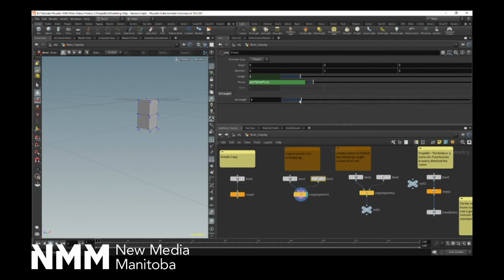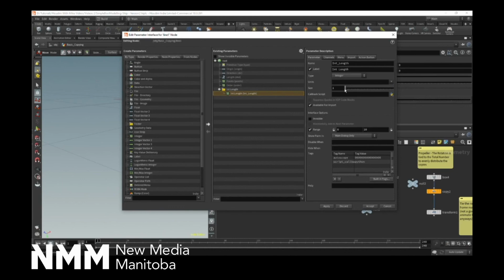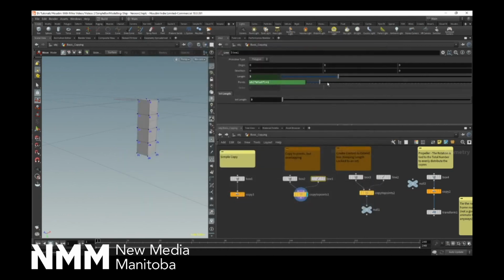It's really powerful. Another thing that I was having some problems with is, it seems to be okay now, but if I wanted to set a maximum or minimum range, you can also specify that. So if I go back into my parameter interface and select this, now I can set the default one. I can even set units, and there's all sorts of stuff here. But I can set a range. So say I only want it to go between 3 and 9 for some reason. Now this control only goes from 3 to 9.